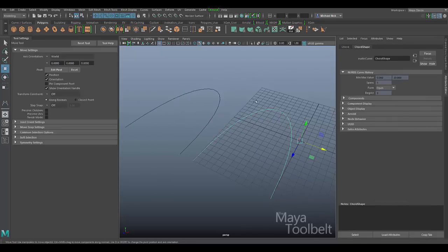Now, the usage of the parameterization of the curves is varied. I mean, it really depends on what you're going to use the curve for. Textures, for example, will display better on a surface that was created with curves using chord length knot spacing, as opposed to uniform knot spacing. That's just how the texture kind of displays on it. With uniform knot spacing, the pro is that it's much more predictable what your parameterization is. It's 0 to 1. This one says 0 to 20.